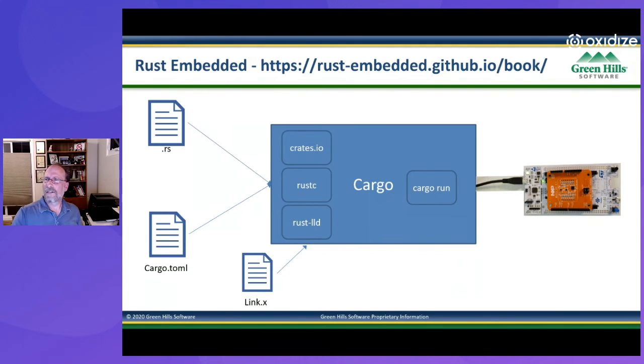And then you've got the cargo run command that doesn't just shell out. It actually talks to this part of the board here, what's called a small JTAG run control thing. They call it ST-Link. And cargo run for cargo embedded actually talks to this thing and resets the whole board and flashes memory images through this and provides your debug interface. So really it's providing a link map and cargo run. Okay, and that's what's different here. Oh, and a bunch of really awesome crates.